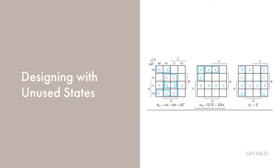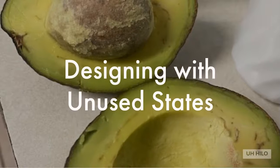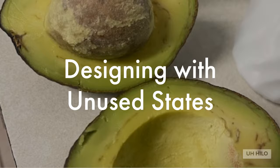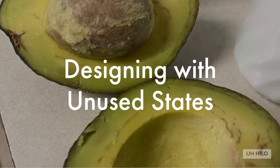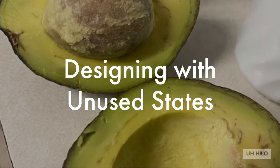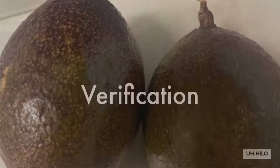the unused states. Thus, it's sometimes useful to specify fully or at least partially the next state values or the output values of the unused states. So, what to do with those unused states? There are several ideas. 1, the output of the unused states can be specified so that any actions that result from entry into and transitions between the unused states are not harmful. 2, an additional output may be provided or an unused output code employed which indicates that the circuit has entered an incorrect state. And 3, to ensure the return to normal operation is possible without resetting the entire system, we can specify the next state behavior of the unused states.